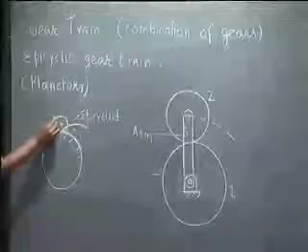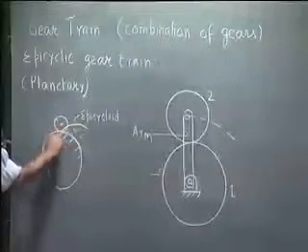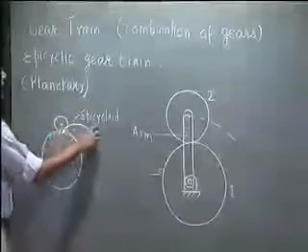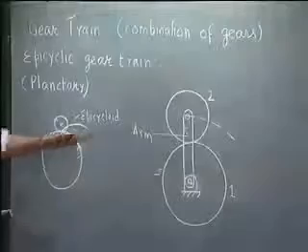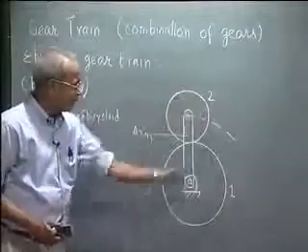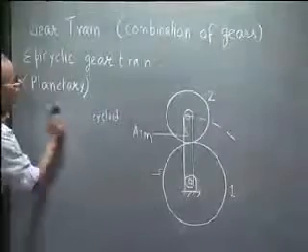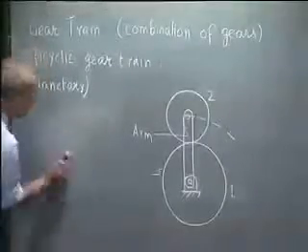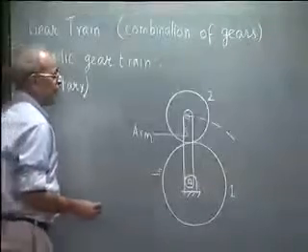The curve that a point on this rolling wheel generates as it rolls around this circle is called an epicycloid, and from there came the name epicyclic gear chain, as a point on this gear will generate an epicycloid. Let's not bother so much about the name epicyclic or planetary. What we should note is that this is a 4-link mechanism.